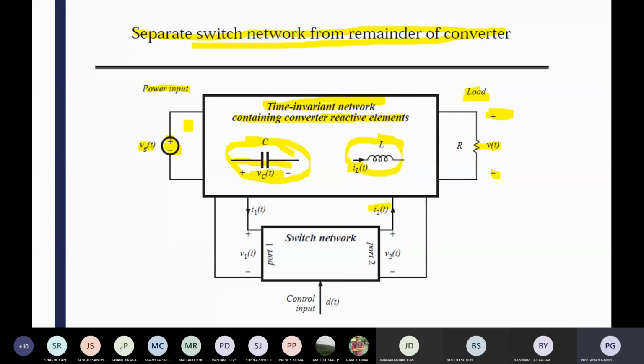It totally depends upon the rating of the panel. So voltage and current, both parameters, are important. You are not bothered about the output voltage; you only have to maintain the maximum power point. That is the prerequisite.